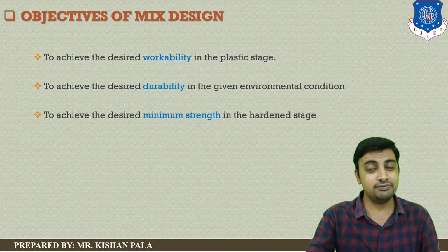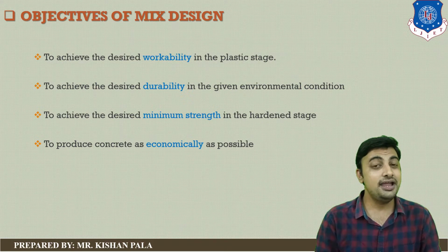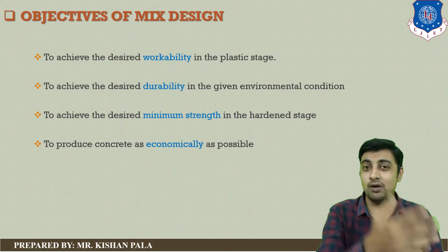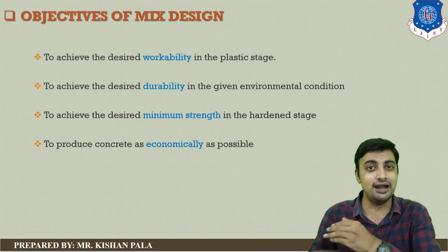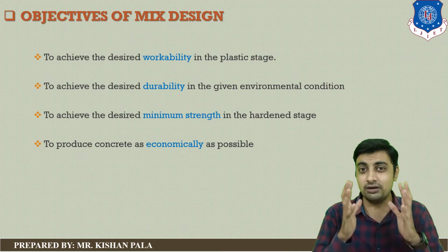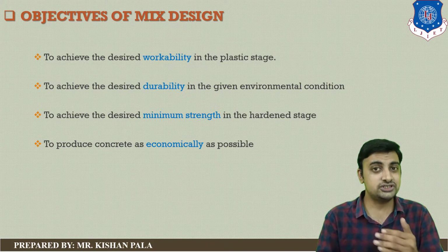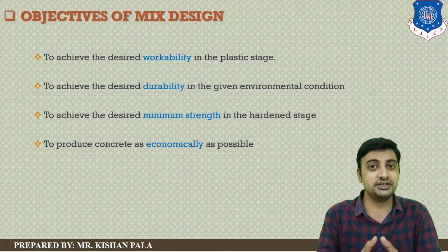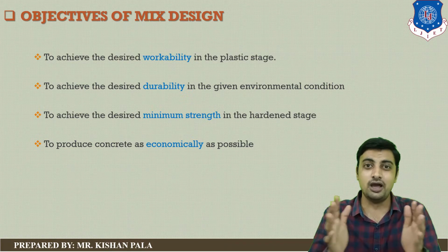So this is one of the important points, and I would like to add one more point, which is that it should be economical. It doesn't mean that you add more cement mass to achieve a higher grade of concrete, higher durability and higher workability, but you are not making an economic concrete mass. Then the structure will be uneconomic. So you should also consider that it should be economical also.